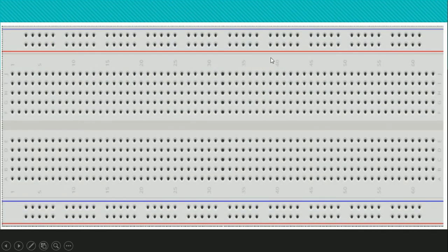And then this is the typical breadboard. They have this color coding. Red means this line is for positive, and this one is also for positive, and the blue one is for negative. Actually, it doesn't matter if you connect the positive to the blue or the red to the negative, but just to follow the standards. If you have many components connected, you won't be confused where to put the power source and the ground if you follow the standard colors for positive and negative.